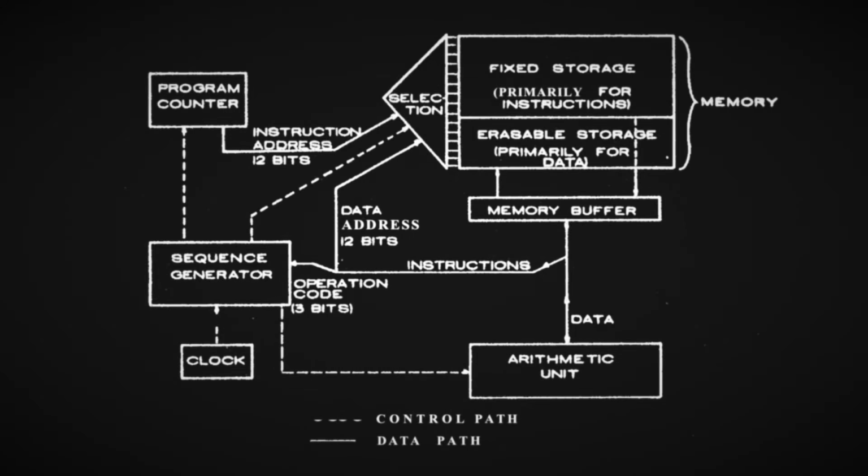The clock component provides a 1 MHz signal for the sequence generator. The clock's main components are a 2 MHz oscillator and a clock divider logic. The sequence generator then provides all the clocks and timers needed for the operation.